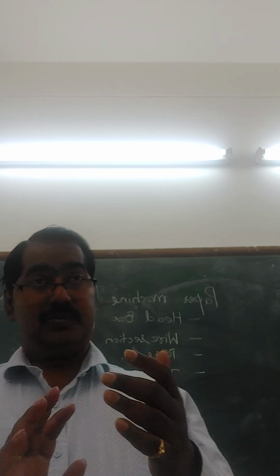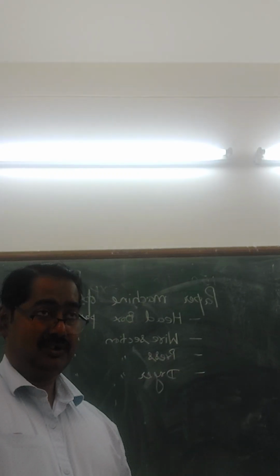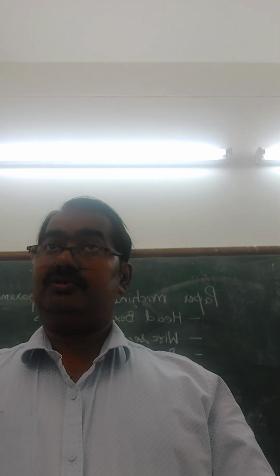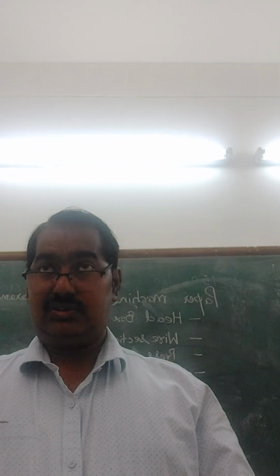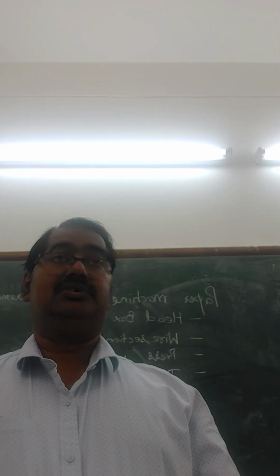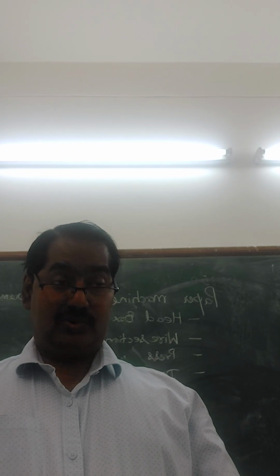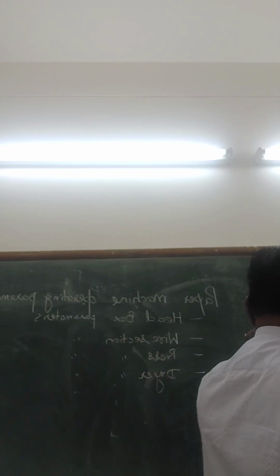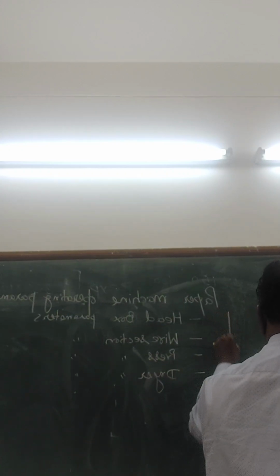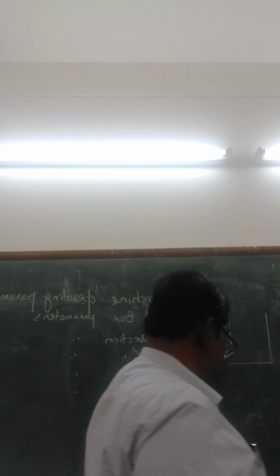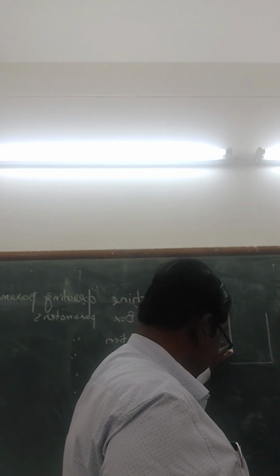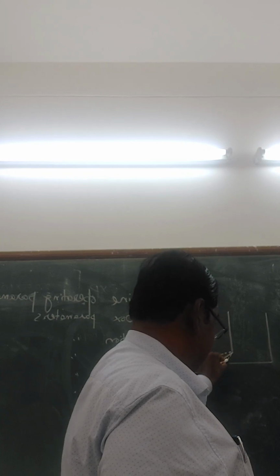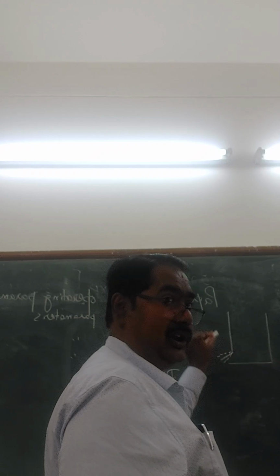What is the second important point? That is the opening, or slice opening, of the headbox. You can adjust the fiber orientation by adjusting the slice opening. There are two types of slice openings basically. You see the headbox slice opening, it's like this one. And this upper slice can be adjusted. The angle can be adjusted here.